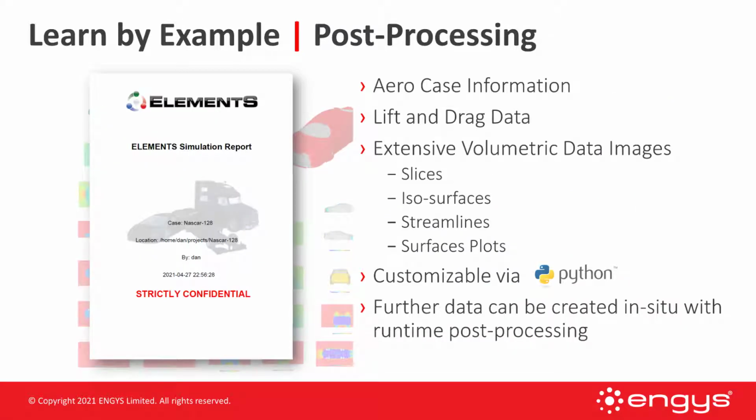And within this report, we're given aero case information about when it was run, how many cores, who ran it, how long did that case take. There's extensive volumetric data and images, like I mentioned, for slices, isosurfaces, streamlines, surface plots. All of this is customizable via Python, and further data can be created in situ, meaning while the simulation is running with runtime post-processing.